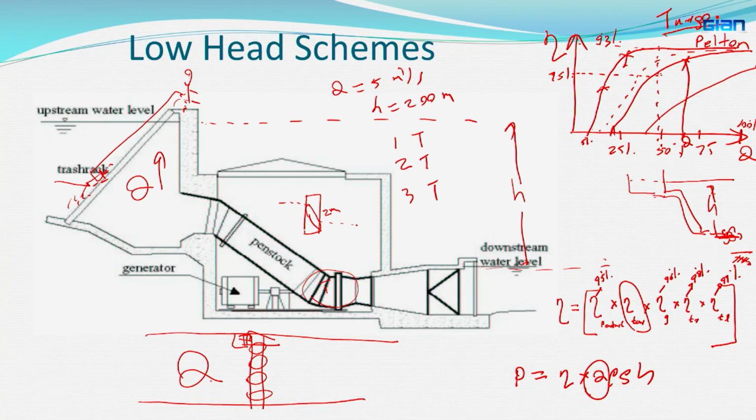Okay. Sir, next question is, so many turbines are there, so how to select the turbine type for low head schemes? Which type is suitable? That we will discuss during our turbine discussion. There are turbine selection charts given by IEC, and manufacturers also have given turbine selection charts depending upon your rated flow and the head. Sometimes you can choose among multiple turbine types, then you can select as per your option. But we will discuss turbine selection charts at the appropriate point in our discussion.